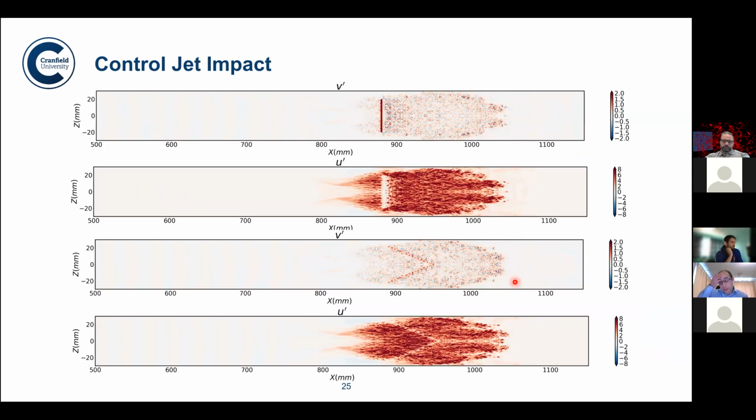And the actual results from that are a bit mixed, in the sense that in the direct vicinity of the jet, just downstream of it, there is a slight calming of the flow. So there is a bit of a benefit just by the fact that it's lifting the spot up. However, on the sides, what we get is an increased intensity region, partly because of the micro shear layers from the sides of the jet developing, and also just because sometimes it's extruding beyond.